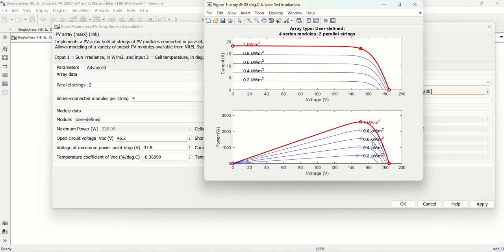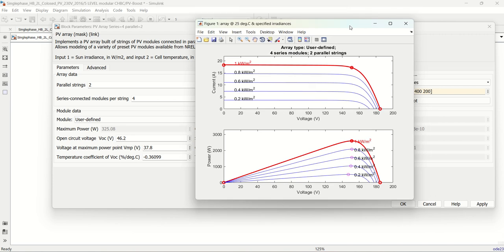Suppose you say, sir, my simulation is going to extract the maximum power, then how do you prove that? Whatever power you calculate should match this. Exactly it will not match, because there will be some switching losses. If it is near to it, that is also okay. This is how you can check your data.